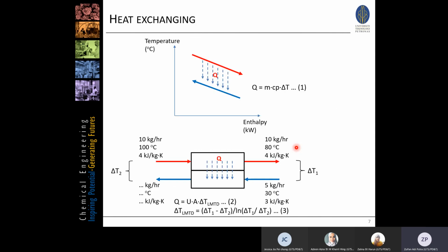So I don't know if we have to go through this concept, but in any case I will explain this graph, because it is going to come up every now and then in this pinch analysis. We have temperature on the y-axis and energy, enthalpy, or duty on the x-axis. A hot stream is a stream that needs to be cooled down, so the temperature goes from here to there. This T1 is higher than this T2, meaning we are reducing the temperature, so this is a hot stream.